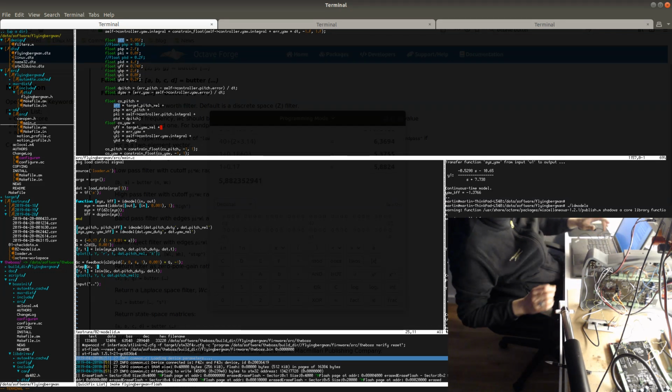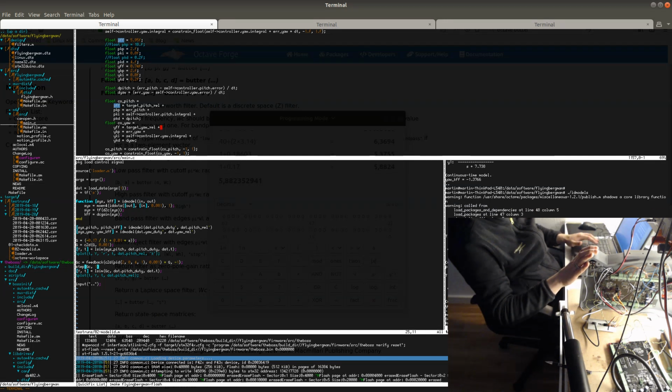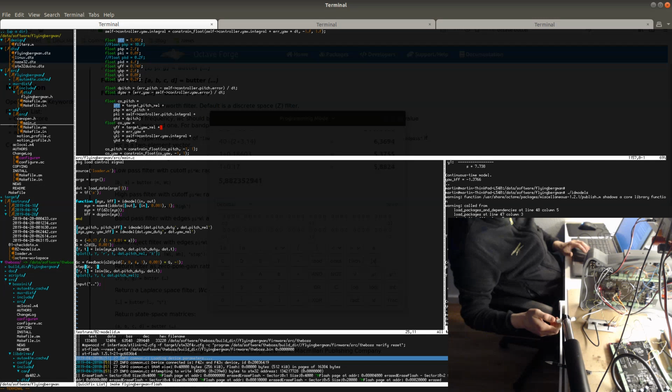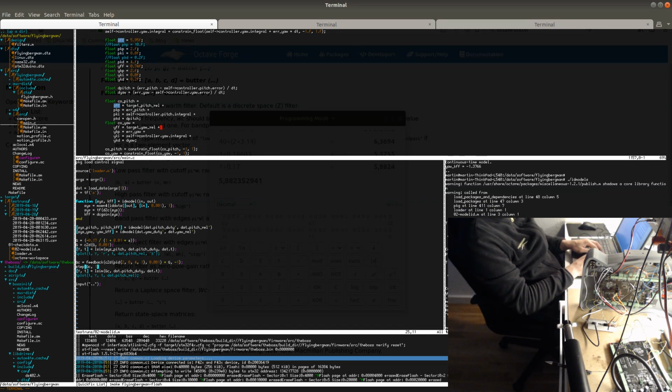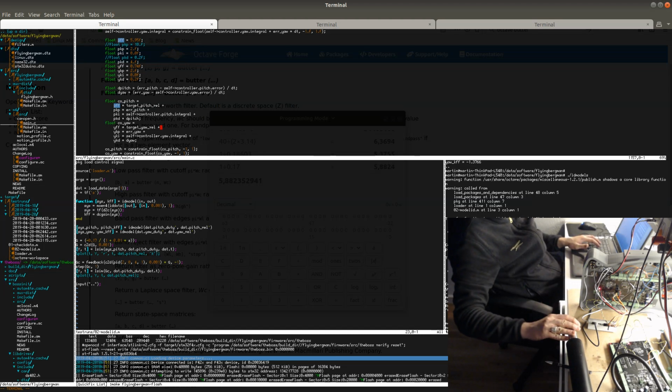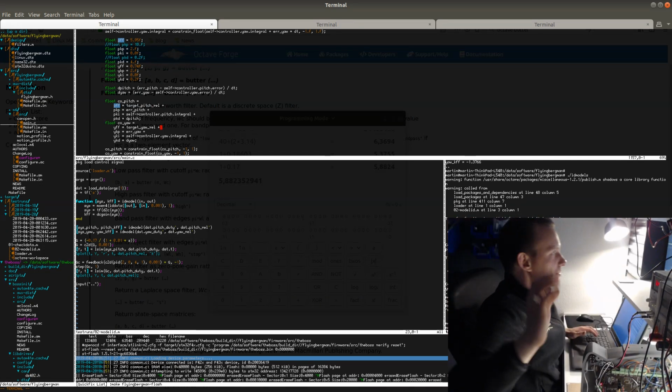Now I'm going to move it to the program position. I don't think this was too bad, but I can hear it clicking. So this D value is way too much, and the simulation shows that it's too much.